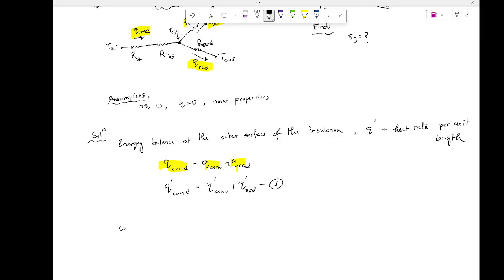Then you're going to understand. So the conduction can be written as... Matt, you understand why I'm doing it? I have these 2 resistors, the solid resistances, the conduction ones. This is my steel and this is my insulation, right? When I put 'st' it means steel, 'ins' means insulation. It's a short form. And what are these temperatures? You remember T_s,i and T_s,o, right? And the heat flowing through this is conduction, through solids.